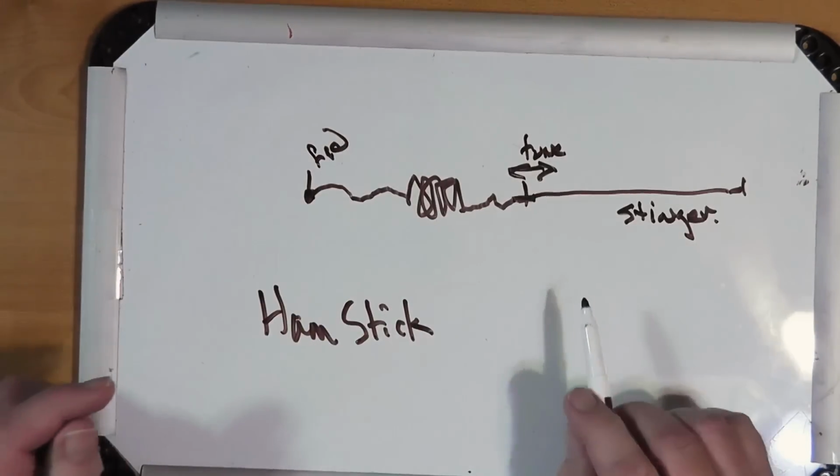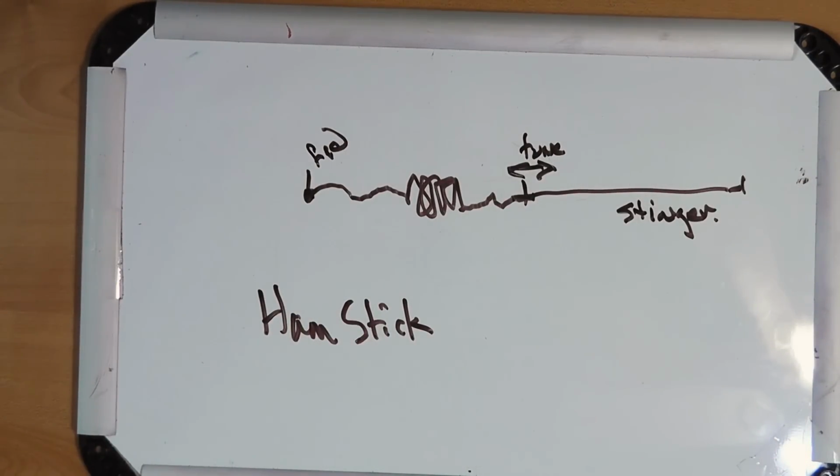Now, this right here, for 80 meters, I put together an MFJ octopus that they sent me and tried it on 80 meters. And what happens is when you put this loading in here, the Q of the circuit goes up.